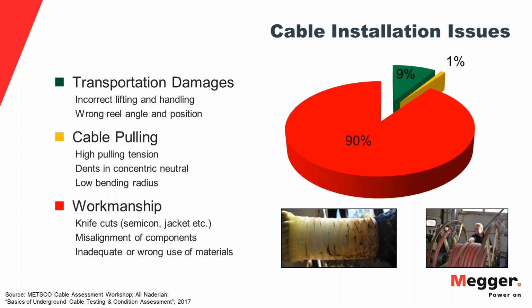Then you have some issues with cable pulling, which always happens, and transportation issues, including, by the way, I didn't write this here, storage issues. Actually, when you see various utility yards, you can sometimes immediately tell if certain cables will cause you problems down the road, because there's a specific way of storing the cable drums. If you don't do it that way, let's say you put them upside down or flip them over the wrong way, that will cause sooner or later at least some mechanical deformation of the cable drums.